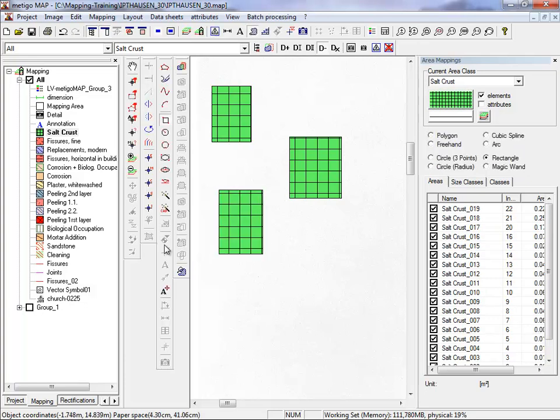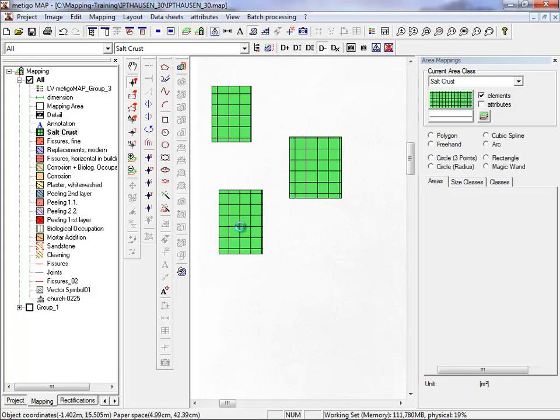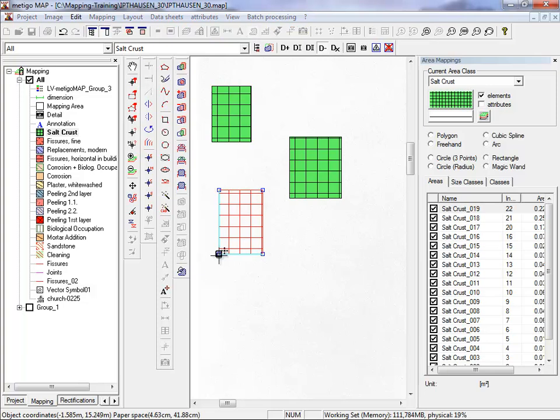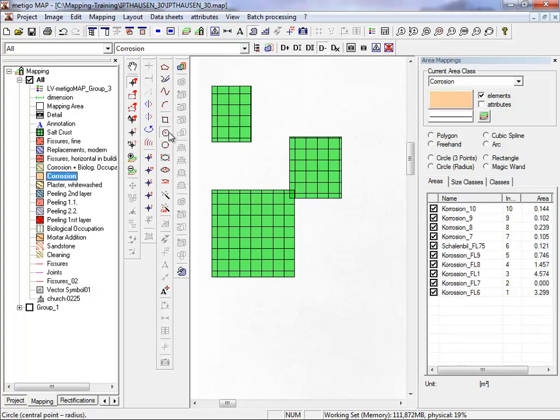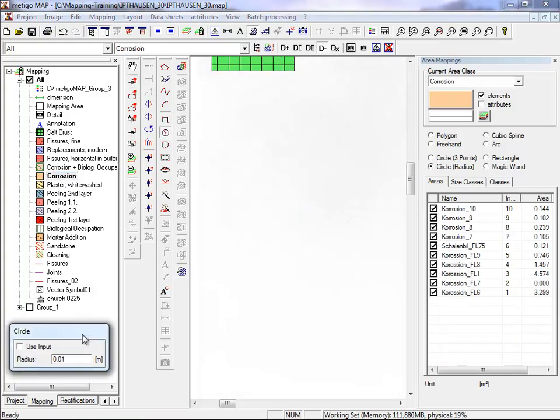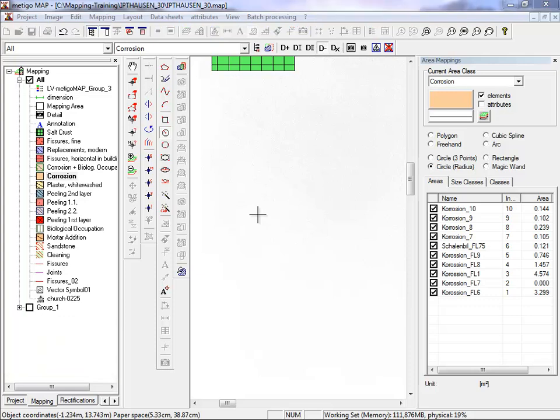We go on to the next set of mapping tools. You can draw rectangles. If later on you use the hammer tool to adjust a point, the rectangle form will remain. The next function is for drawing circles. When activating the tool, this small pop-up dialog opens that measures the radius of your circle after you drew it.